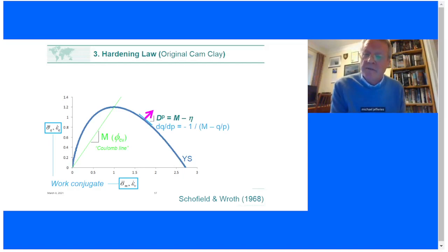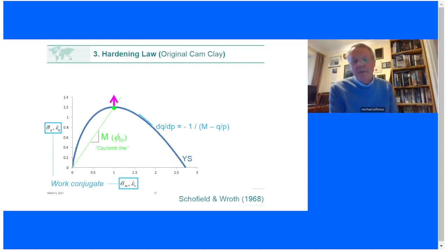That's the yield surface. Okay, and that's how it's been determined. We've taken a theorem, and we've taken the Taylor-Bishop strength idealization, and we've integrated. And that gives us our yield surface. Now, when you do an integration, of course, you always get an integration constant. And what these guys did, they said, okay, we like using the vertex of the yield surface, which is where the green dot is. We're going to take that as where we're going to define the integration constant.